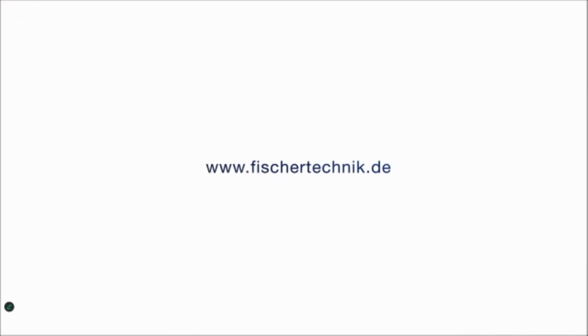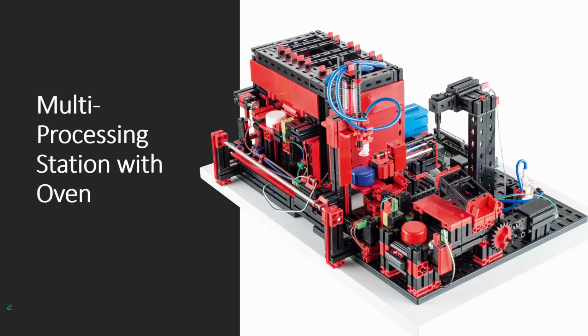Anyway, getting back to brass tacks, the dimensions of the model are approximately 19 by 28.5 by 15 inches. It has a weight of 18 pounds. Again, the 24-volt version has a relay board for motor polarity reversal, a multi-pin connector, 34 pins with a grid of 2.54 millimeter, as well as additional PCB terminals with push connections for all inputs and outputs. And you do need to provide your own PLC and programming. There is a 9-volt version available, which comes pre-wired to a pre-programmed robotics TXT controller, and you need one power adapter for that. That was a lot of talking. Next up, we're looking at the multi-processing station with an oven.